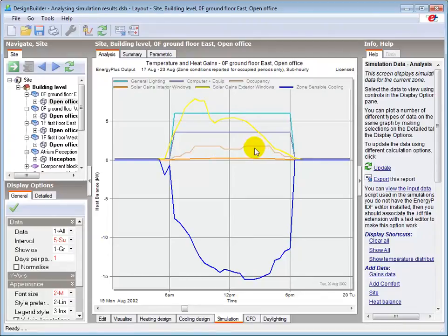You could review and possibly alter these in the Activity tab if you're sure they don't represent your own design criteria. However, note that these values may have been taken from the schedules based on the national standards, so beware of changing them when undertaking Energy Code compliance simulation. The final internal gain shown is that due to internal glazing.